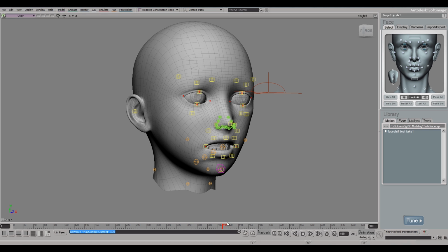with the Faceshift capture workflow, you're going to want to use the OpenNI drivers, which means you can't run Faceshift on the same computer that you're running Brekel ProFace, because Brekel ProFace uses the Kinect SDK drivers, and you'll break Brekel ProFace if you install those drivers and the OpenNI drivers together on the same computer. That's why I had to use a separate computer.